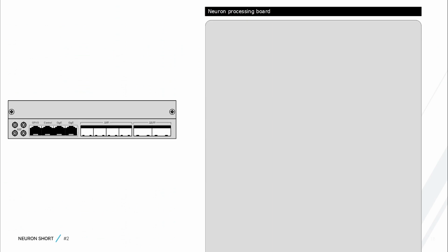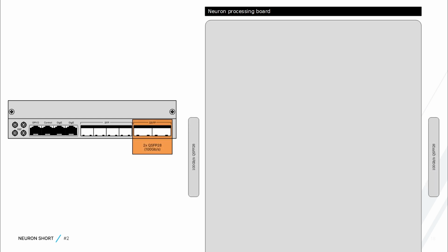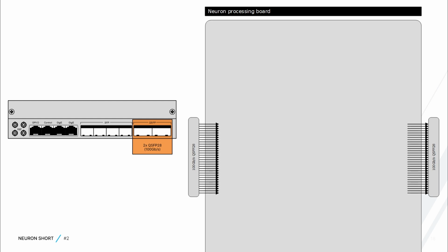To explain this structure, I'm going to draw a block schematic you might be familiar with from Synapse next to a connector panel of a Neuron board. First, there's the IP I/O. Our QSFP interfaces, of which there are two for redundancy, are truly single MAC 100 gigabits per second. In the software, a certain amount of IP audio and video input and output streams is defined.